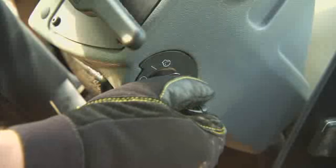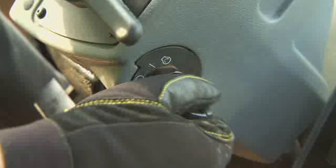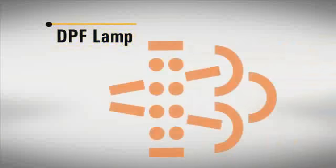Whenever a machine's key switch is turned off, the system defaults back to automatic mode. If you had regen disabled, you'll need to press the switch again when you restart the machine. The DPF lamp illuminates when the soot level reaches 90% and above. It alerts the operator that regeneration is required.